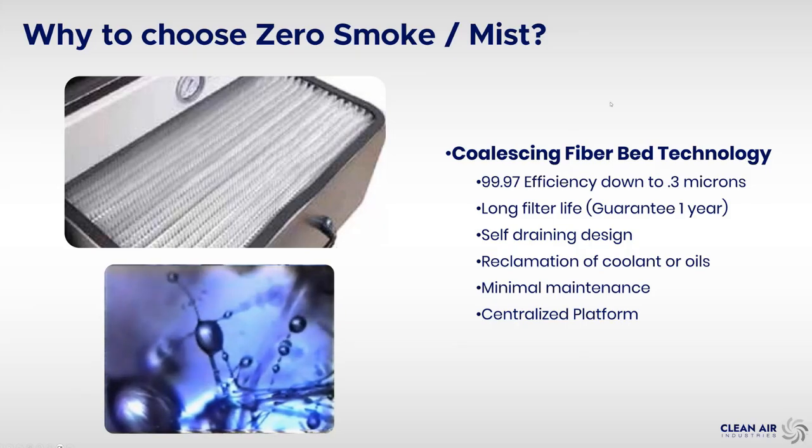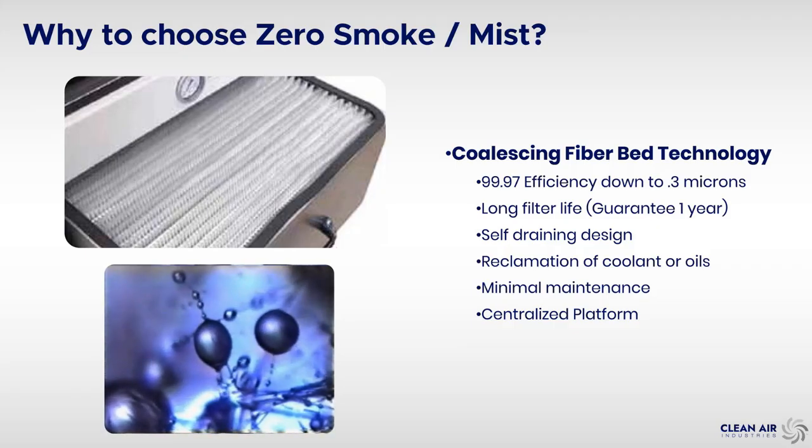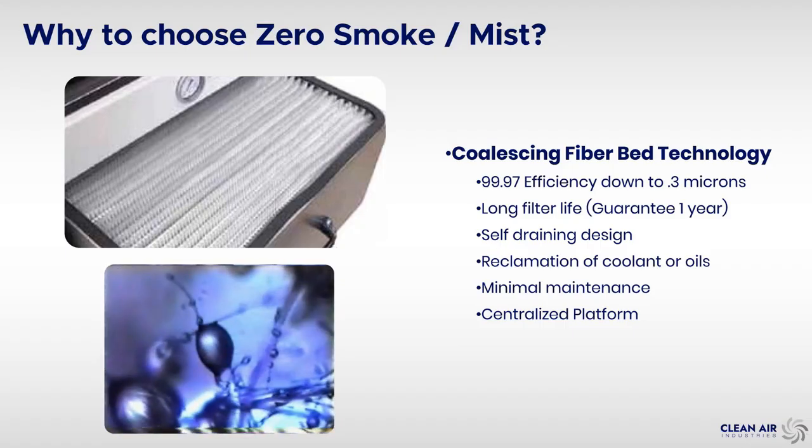As I said, we offer 9 different collectors out there, and within those 9 collectors, you can actually gang some of them together to get twice the CFM. But what makes the technology that we use so good is it's a coalescing fiber bed technology. And you can see down on the lower diagram, that's a microscopic camera little video that we did of how our media coalesces the mist when it gets introduced into the filter.